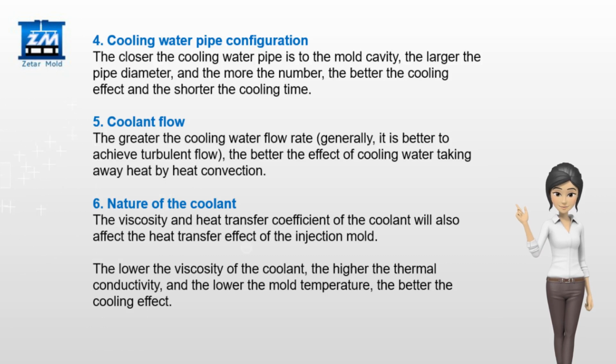Cooling water pipe configuration. The closer the cooling water pipe is to the mold cavity, the larger the pipe diameter, and the more the number, the better the cooling effect, and the shorter the cooling time.